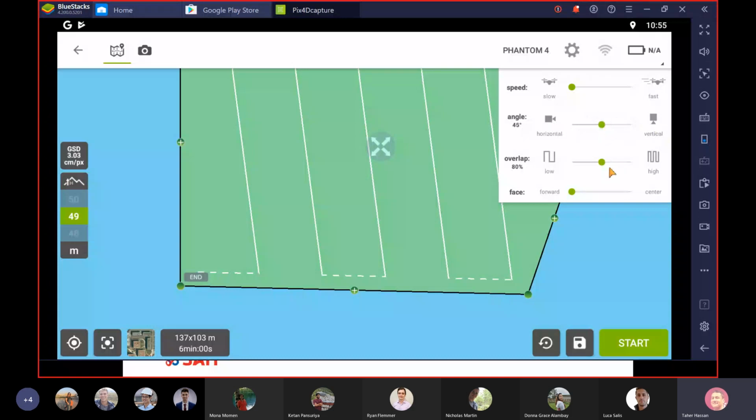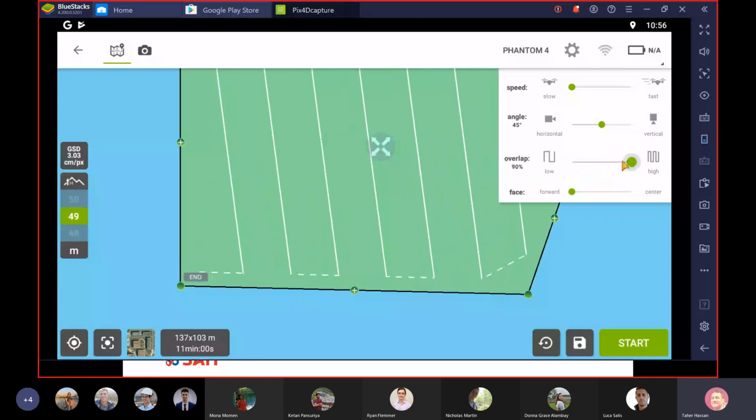Okay. Also, you can control the overlap percentage. This is a big discussion. So just please remember this number because I have a discussion. I'm not sure if it's going to happen today, but we must maintain an overlap between the images. And that's something that we already discussed, okay? That any random images cannot be used in photogrammetry. To use the image in photogrammetry, your photos must overlap. So when they overlap, it means my object will appear in 2 photos at least, and I'm able to create a 3D model, okay? So you can control the amount of overlap by this slide bar here.